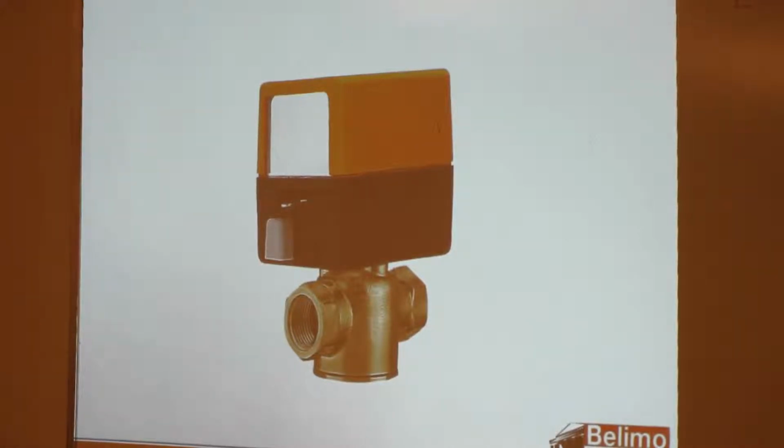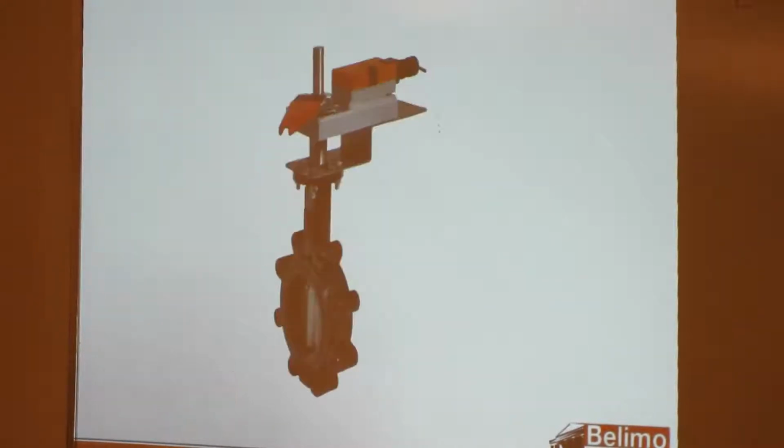Anybody tell me what that is? Yeah, with Belimo, we only have it as a 2-position. It's a zone valve. If you need to do modulating, then we always recommend going to the CCV. How about that one? Pretty easy one there, butterfly valve.